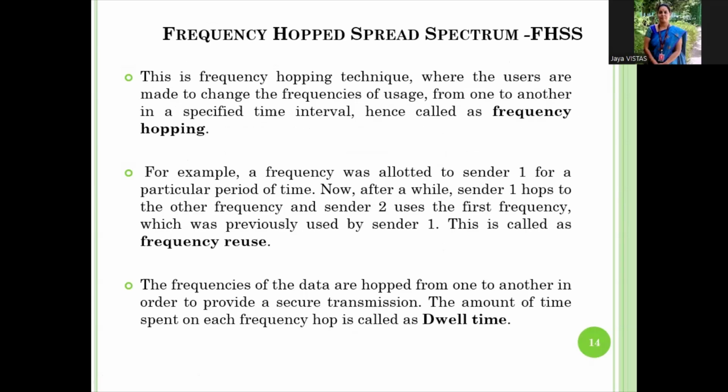The next one is frequency hopped spread spectrum. This is the frequency hopping technique. Here, the users are made to change the frequencies of usage from one to another in a specified time interval. The users can change the frequency usage for a fixed time interval, hence it is called frequency hopping.